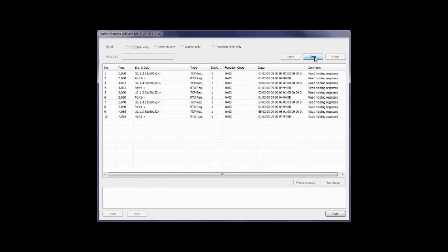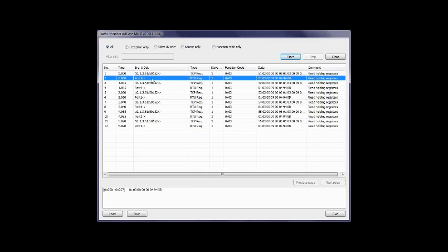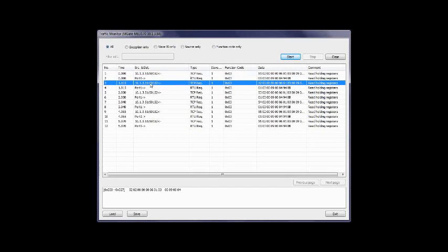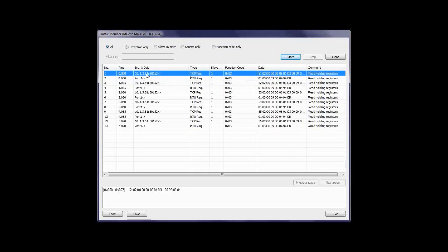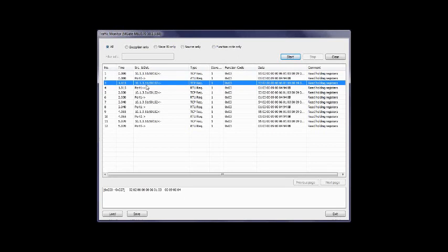Oh, okay. So with this, what we can see here is we have a request coming in on Ethernet via TCP. I see that out of port 1 of my gateway, I'm sending a request on RTU, and I see no response coming back. So again, coming in on Ethernet, going out serial, and since we know that this is a request-response protocol, we should see something coming back, and I don't see it. This tells me that I've got a problem between the gateway and my attached device.